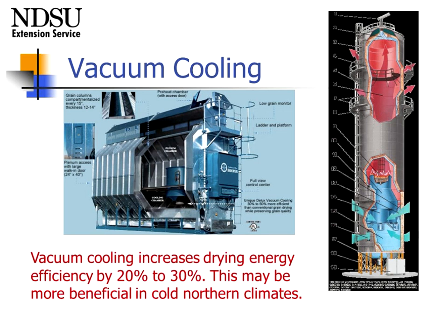As I indicated, this vacuum cooling can increase drying energy efficiency by 20, some will even say up to 30%. There's been a lot of tower dryers that have been sold based on that principle, because we're pulling the air in through the bottom portion, up through the burner, and out through the top. That same principle works, though, in a horizontal dryer as well.